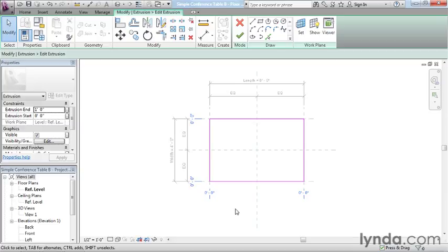You can leave these. If they're giving you what you want, you can use them just fine. There's really no reason otherwise. But sometimes the automatic sketch dimensions will actually start to give you results you weren't looking for, usually when the forms get more complicated. So we'll probably have some opportunities to discuss them again in later movies when the forms start to get more complicated.